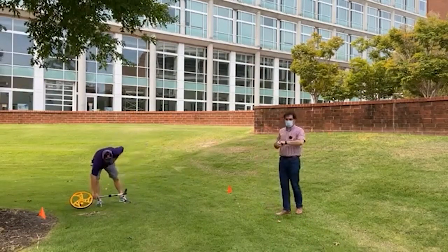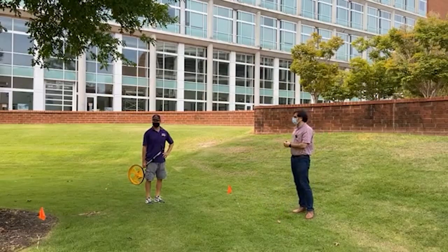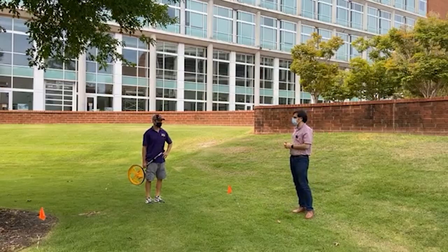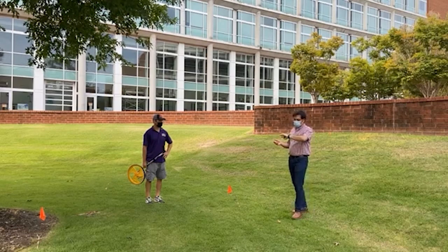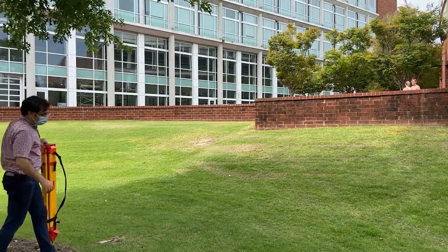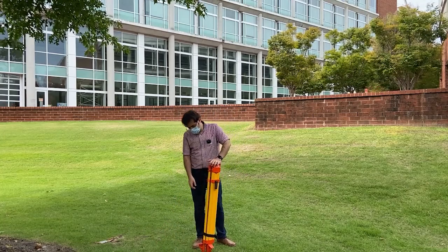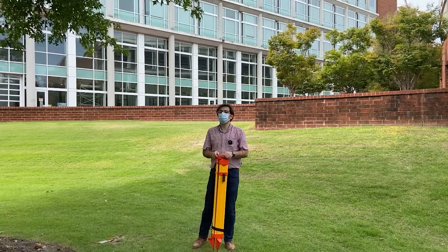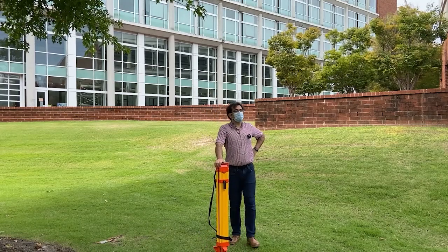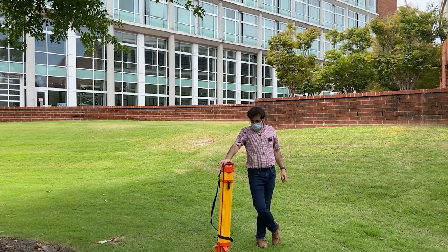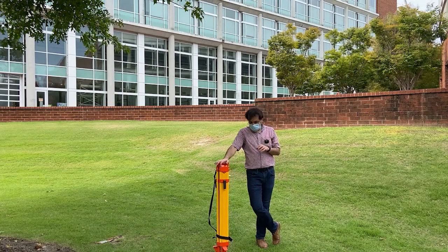Okay, today is a sunny day and the weather is 86 degrees. As you know, we need to report the temperature and weather as professional surveyors because it impacts our results. The total station setup is basically similar, with some more steps, because for a total station what matters is not just setting it up and making it level, but also making sure it is exactly on the point.